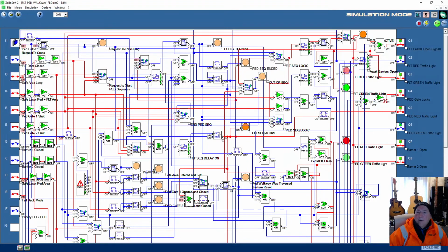I'm just thinking now whether instead of it locking straight away, we have a couple of second delay before it actually locks, just in case you go to open the gate and your hand slips and it just shuts on you, because it will lock straight away. You need a little bit of time maybe. I could always add a timer there if needed. A little bit of a delay. You have loads of timers, loads of delays. You're slowing the system right down, but that's okay sometimes.